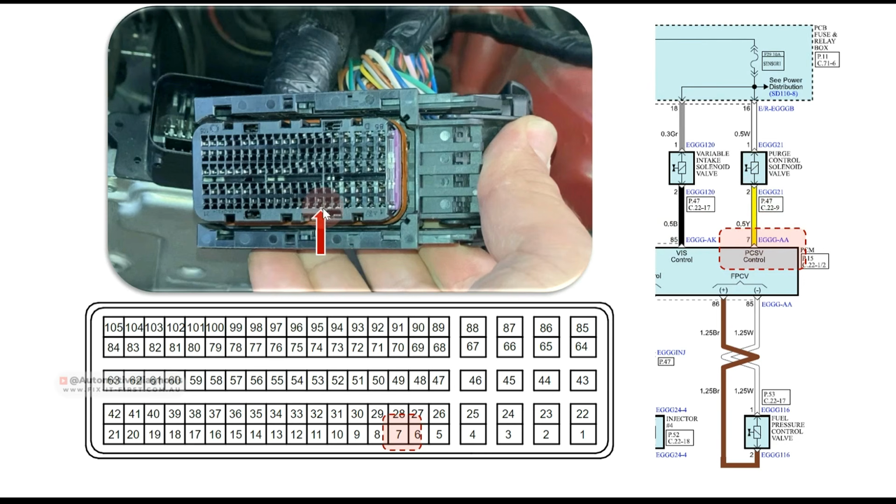If you have a very thin test probe, you might be able to check it from here as well. If your test probe is thick, you shouldn't insert it from this side of the connector. You can just turn the connector around and back probe from the back. And of course, finding this wire from the back is not that big of a deal right now because we found the pin. We already know the color as well, so it's going to be really easy to find it. So this was actually a review of all the sensors and actuators on this engine